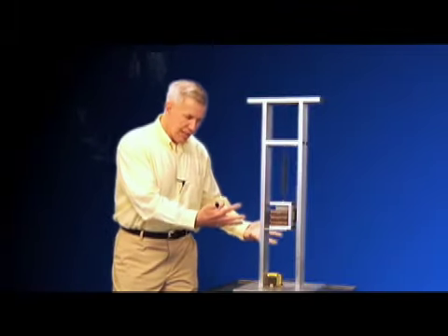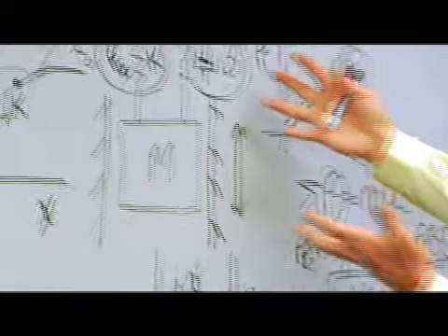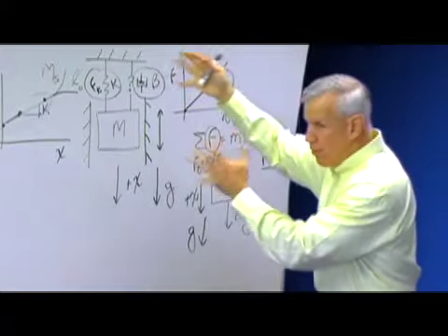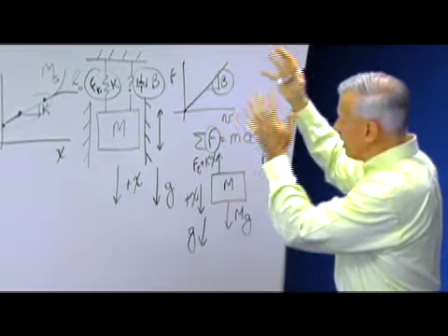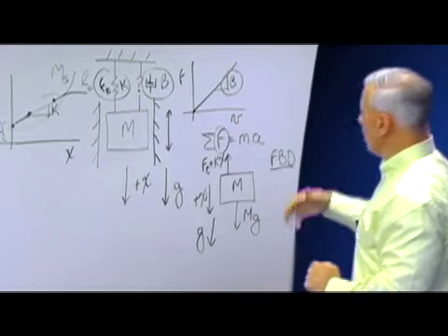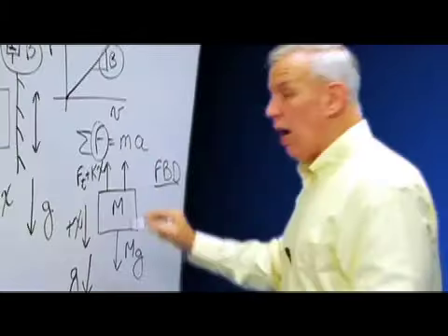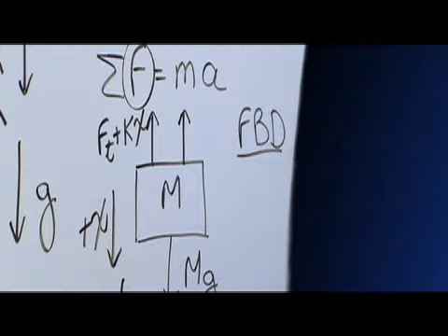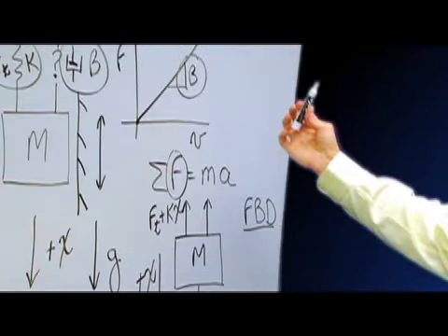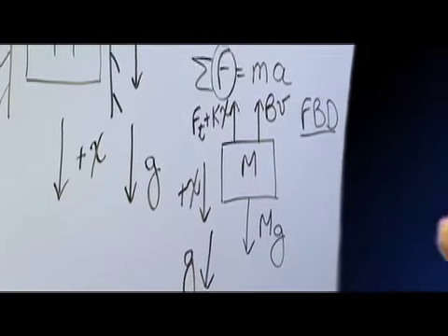Now, we know, because we observe that these oscillations decay, there must be some frictional force acting on this mass. I must capture that effect. I've done so with a pure and ideal viscous damping element, an essential building block. Like the pure and ideal spring, this pure and ideal viscous damping element I will use to capture the frictional effects. That damping force opposes the velocity of the mass. So if the positive direction velocity is down, the friction force acts up, and it's proportional to that velocity.